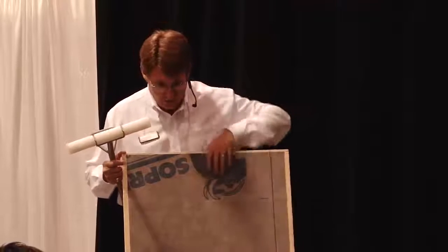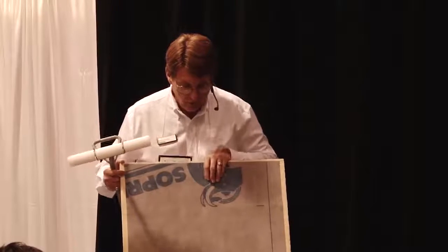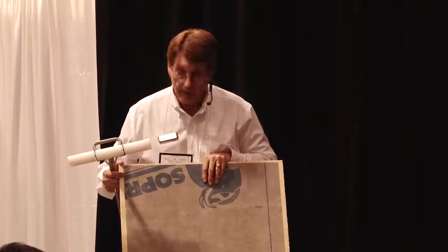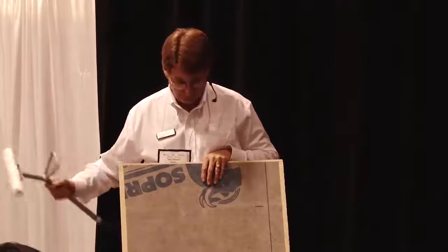PSAs are different than SBS modified membranes. You have an early green strength to the material, meaning the contractor will do his best to align the material to where it's supposed to go. If there is an error, there's something in his way, it is a membrane that can be easily removed, replaced back on, and then you, as a contractor, can finish to remove the release film, keeping it nice and straight.